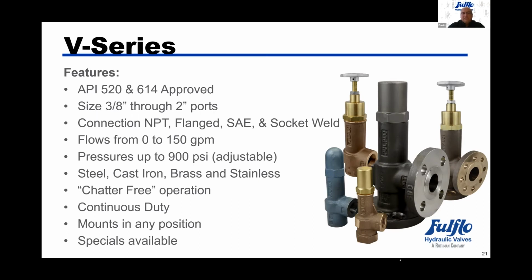They are fully adjustable, and that determines the size. The 1 inch and the 1.5 inch, we can take up to 900 PSI. Normally, our relief valve pressures are up to 500 PSI. But selected sizes and selected springs can get you up to a higher pressure. The steel, cast iron, brass, and stainless steel are the product material offerings for this series.